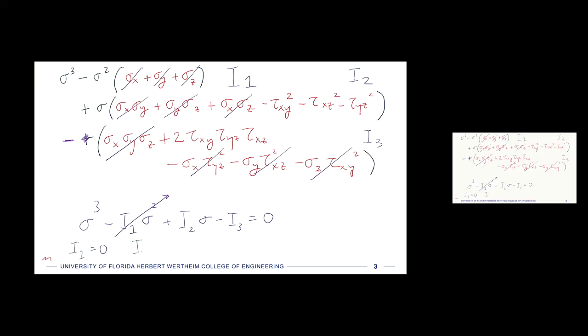So I2 is going to be equal to, if we plug our values in, minus tau xy squared. I'm going to put in all the minuses just for good measure. So minus, and then tau xy is also negative, so negative 75 squared minus positive 65 squared minus negative 55 squared. If we square a negative number, it becomes positive. So then we have 3 negative numbers all summing together. We get a value of minus 12,875, and that is in megapascals.